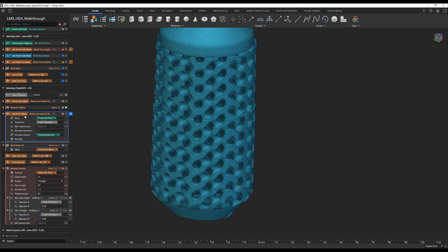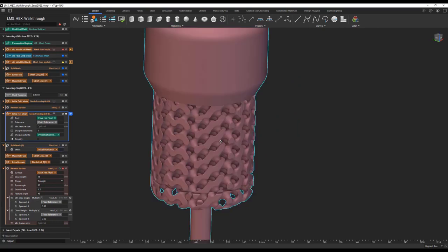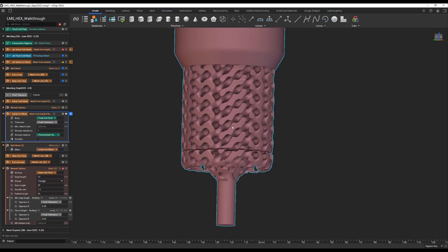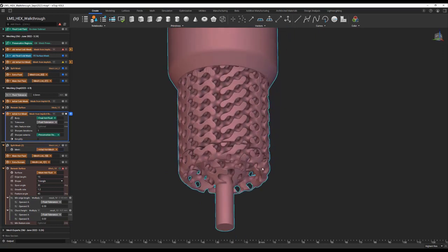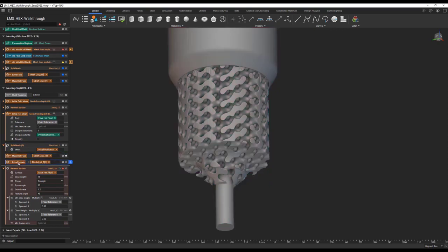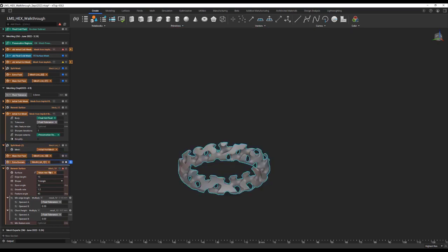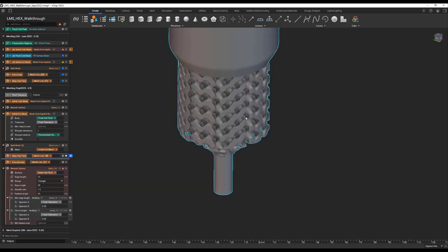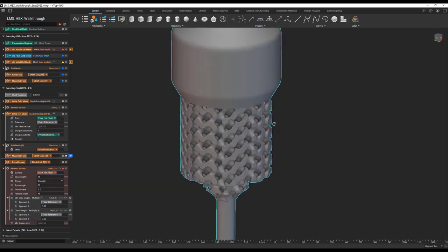In the process of setting this up, I remembered that there were two parts to the hot fluid, the main domain and the extra bit at the bottom. So we use the mesh for implicit body, put that into split mesh, and we'll isolate the two domains. In this case, we're going to mesh just the main hot fluid. So the mesh for implicit body went through.